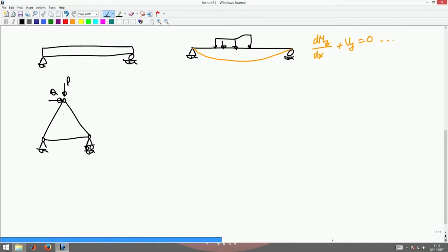That's a good enough argument if the deformations are small, but what happens is these tell you that there is only one deformation that is possible for a given truss, since you are writing the equilibrium equation in the undeformed shape. If the truss were to deform, then you will find that there will be multiple equilibrium states that are possible. To illustrate that, let us look at an example wherein I have this 2 element truss with a point load P acting vertically down.